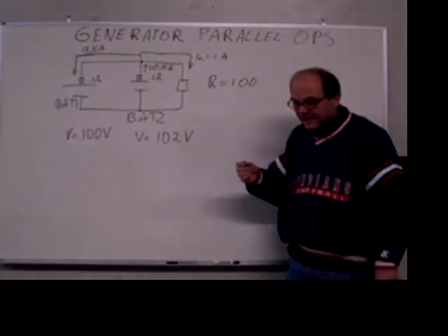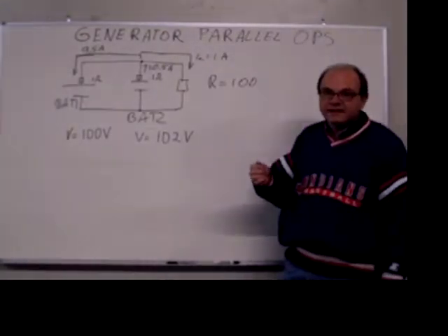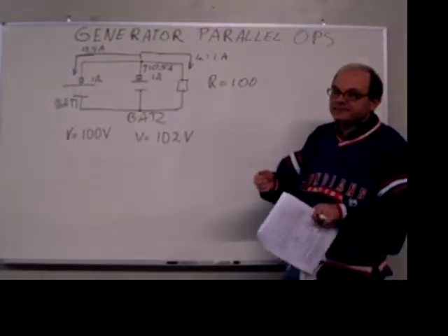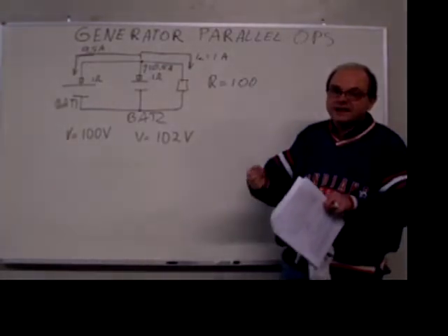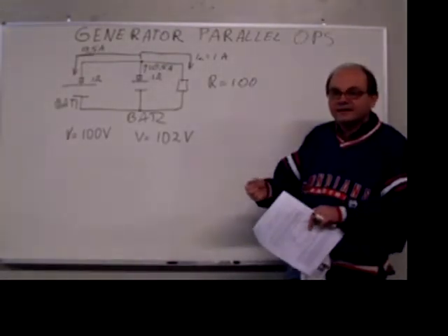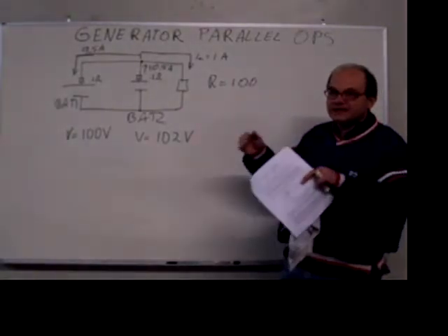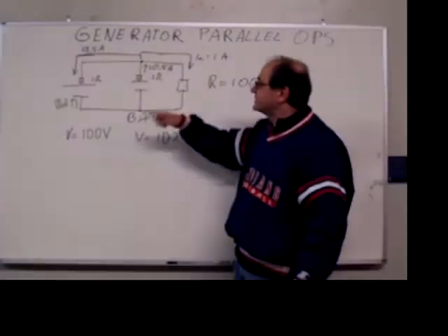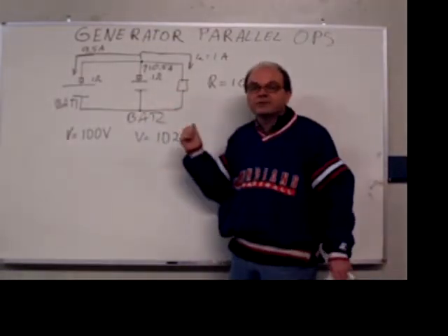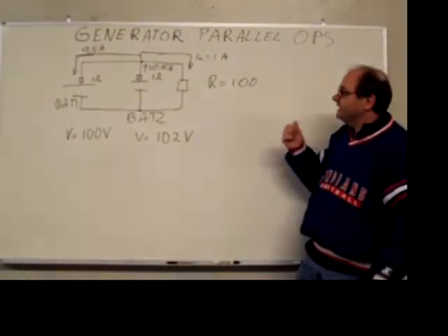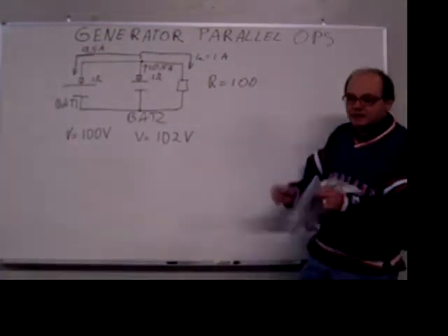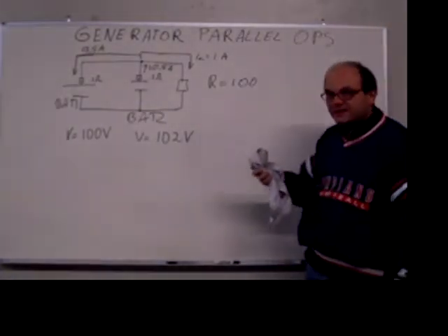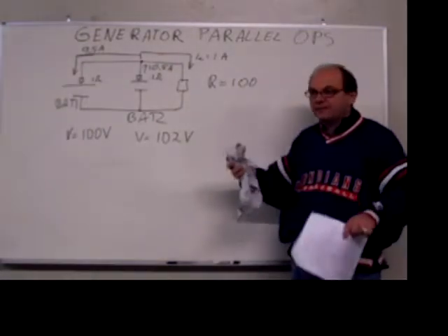So what actually would have to happen is you would have to use a high precision digital meter to exactly set the RPMs equal on each one of these generators, and you will have to set the voltage correct. That means both of these outputs have to be exactly at the same voltage. Otherwise, you're going to have currents going in either direction between the two generators, which are not going out to your load. That is probably the first big part in this whole system, by trying to parallel generators which are not really meant for parallel operations.